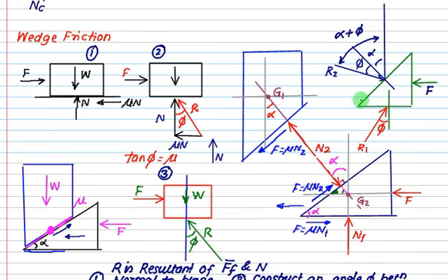For the inclined plane, this one is a normal, this is a normal. Construct phi in the same direction of force, right, as R2, but your normal itself is inclined at an angle of alpha. So the total angle with the vertical is alpha plus phi. So if your plane is inclined, it's alpha plus phi. If your plane is horizontal, alpha is equal to 0.